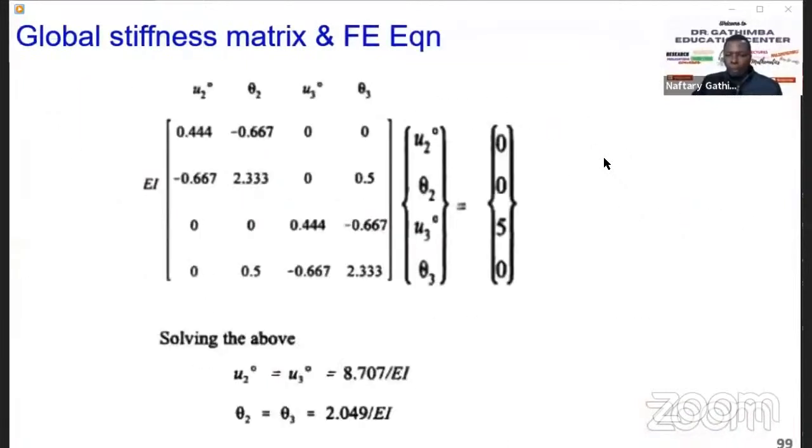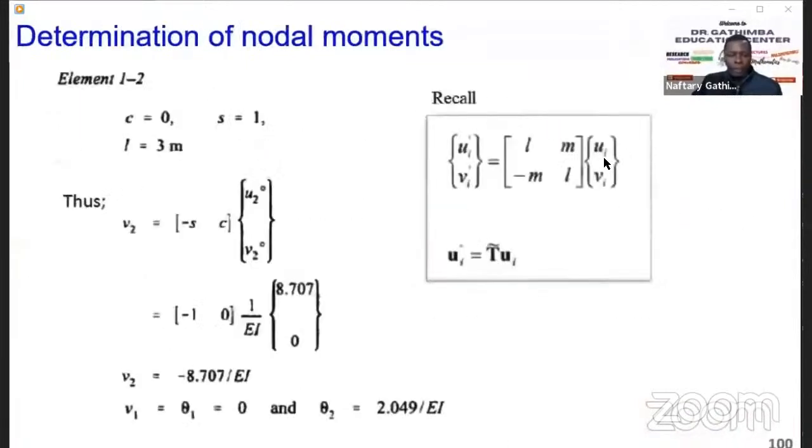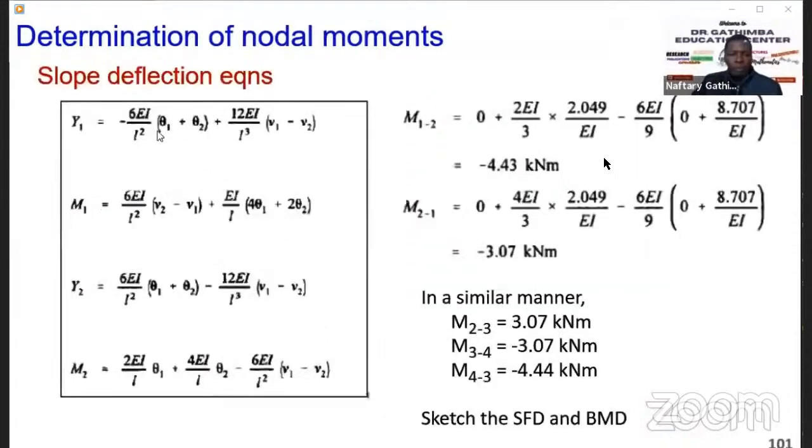So we have reached a point where we've obtained, we were calculating these angles so that now we can extract from the slope deflection equation. We know we need to get V2, V1, theta 1, theta 2, and so on. So once you extract the slope deflection and use the equation for the moment, you can get M12, which is M1, and M21, which is M at node 2.